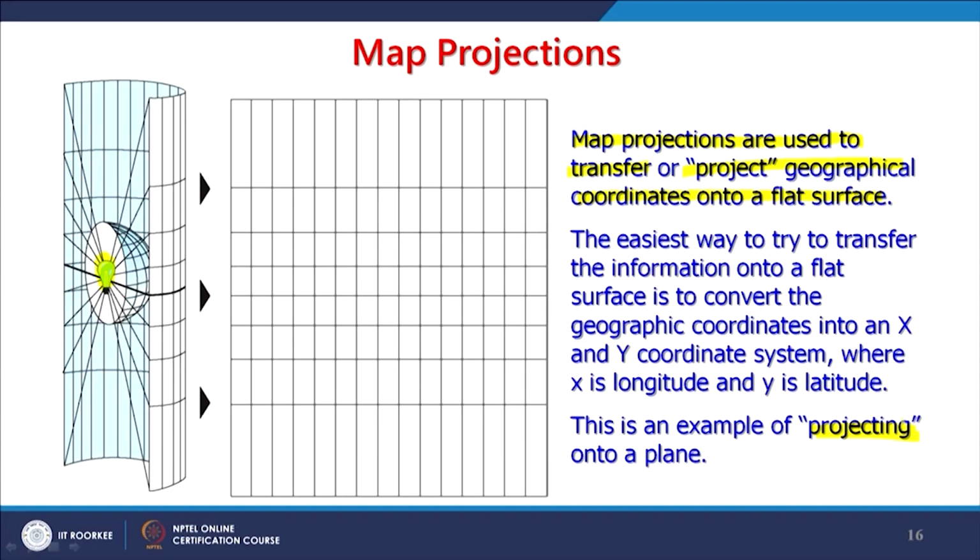For India, if we project in the UTM projection, we get very accurate measurements. So initially you can keep your maps in XY coordinates or in decimal degrees, but whenever you go for measurements, you can temporarily convert to a map projection like UTM, do the measurements, and then come back for other analysis.